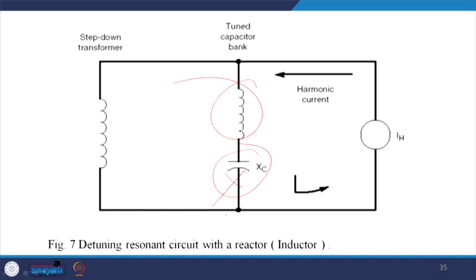Please understand it, because you have to have a high value of the capacitor as well as a good amount of cost comes from the inductor. This inductor you have not connected, it is there because of the leakage reactance of the transformer, but you require to physically connect an inductor and you make it a tuned capacitor bank filter. We will discuss in detail while designing the filter. I have dedicated 1 or 2 classes in total for discussing this entity.